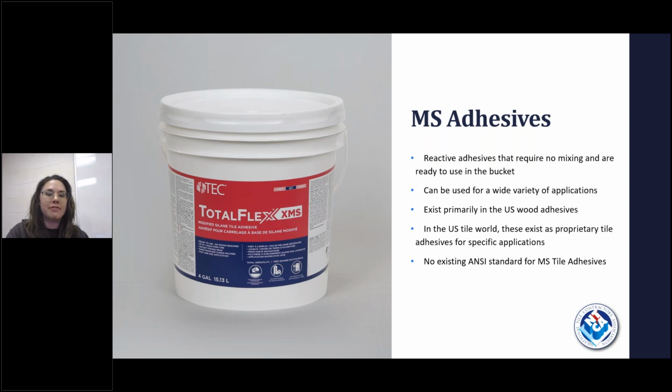MS adhesives are modified silanes. These are reactive adhesives. So notice I didn't say organic adhesives like we would say for Mastics. These are reactive adhesives that require no mixing and are ready to use in the bucket. Typically, they don't have all the same limitations that you end up with Mastics, right? So you can use them for a wide variety of applications.